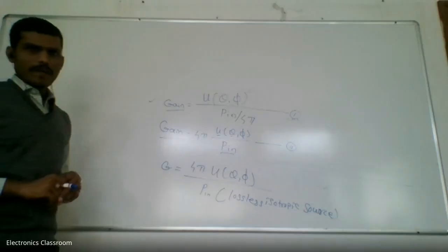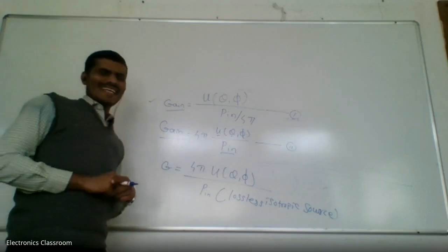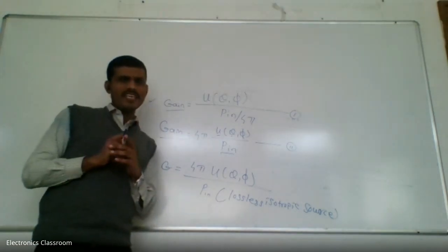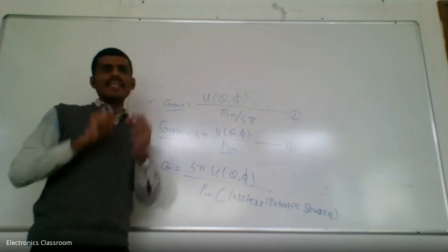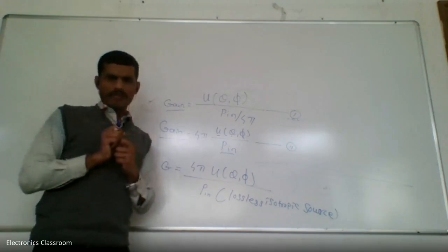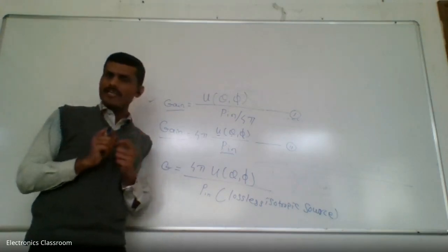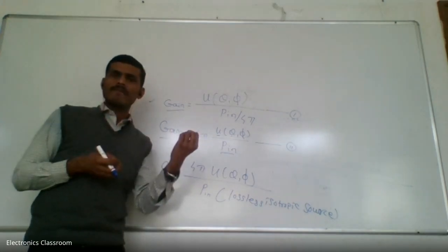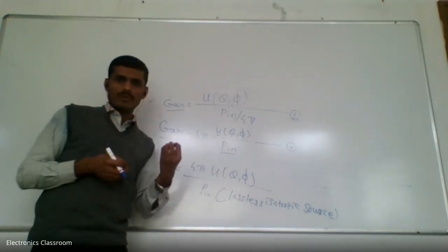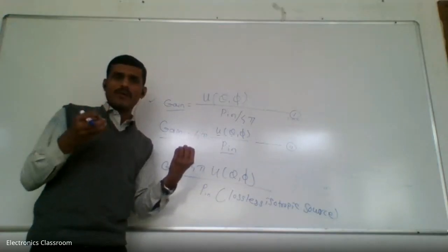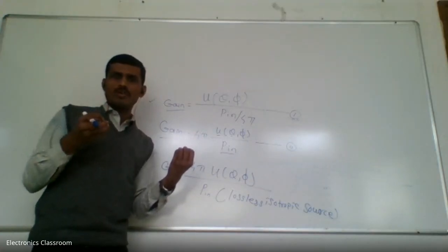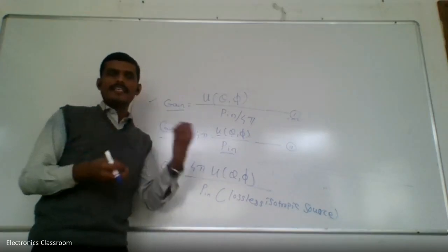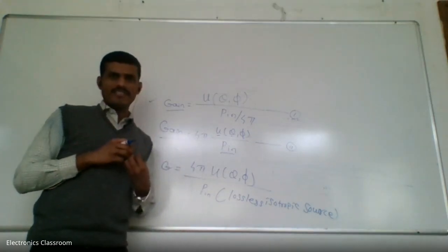Okay. Now we have to discuss antenna efficiency. Is that clear? Now by using antenna efficiency, again we can rewrite the total radiated power. बघा, total radiated power म्हणजे काय असते? Input power गुणिले radiated power. Input power is equal to P radiated divided by your dielectric and conduction efficiency.